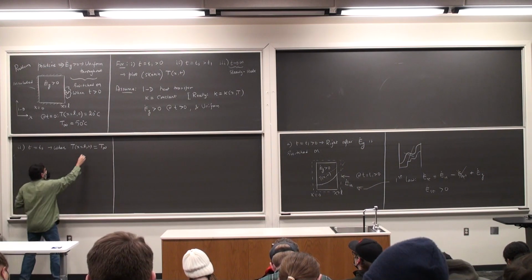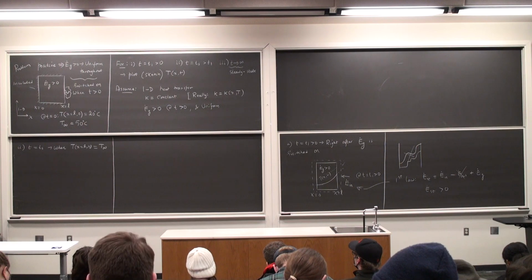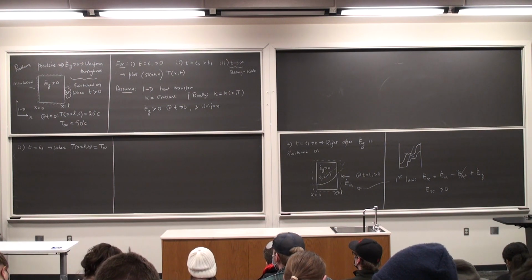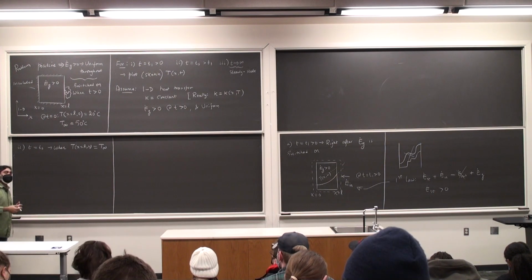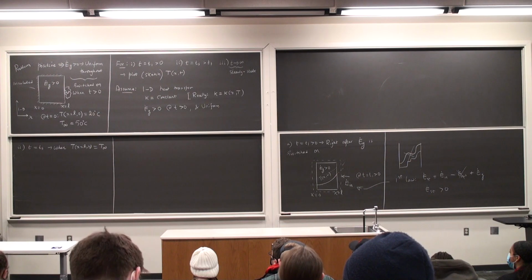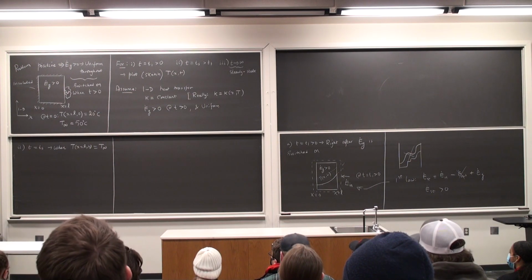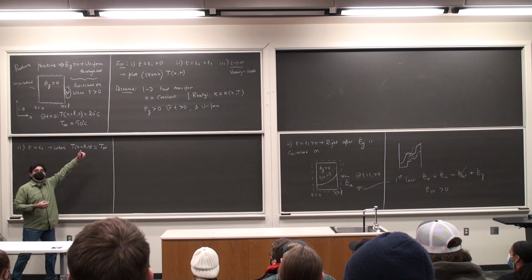This is suffix Ts here. T at x equal to 0 is still going to be some temperature, I don't know what it is. But the slope is going to be 0 there, because there is still no heat transfer across that surface. It's insulated at all points in time. If this is equal to T infinity, then what should be the slope?